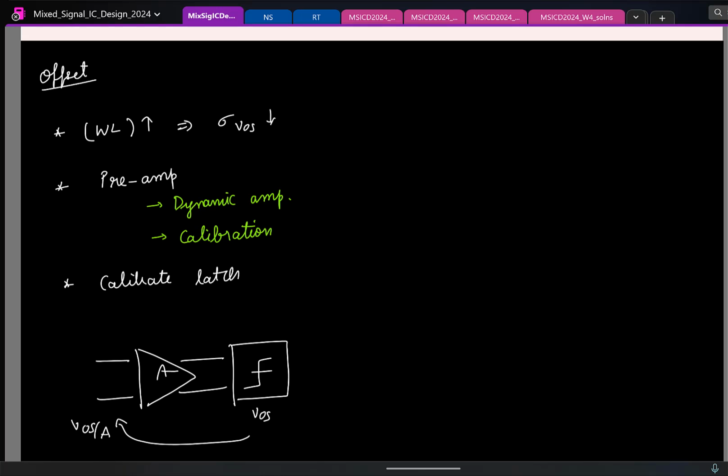We also looked at the issue of metastability briefly. This arises because the comparator is going to regenerate with a positively growing exponential. So if the input is small enough, the comparator regeneration time will also be really long. Say this is the time available for you to finish the comparison.